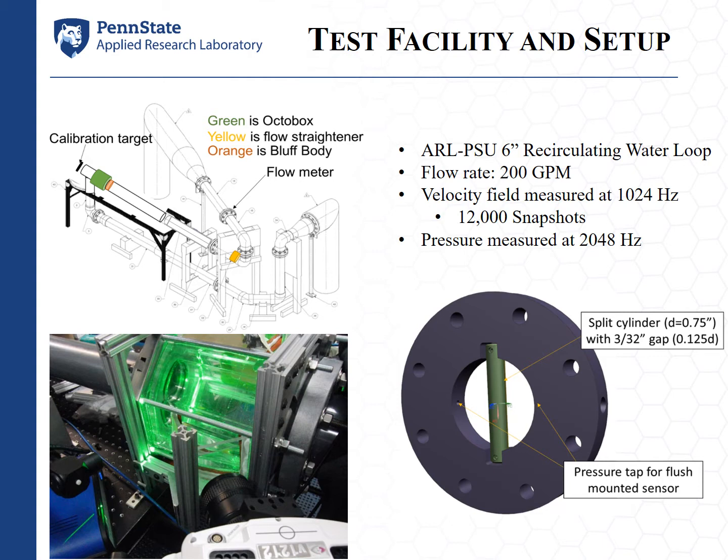So in this work, a split cylinder was mounted upstream of the optical test section. This optical test section is an acrylic pipe surrounded by a water-filled octagonal acrylic prism. This gives us flat surfaces with which we can observe the flow using 4 Photonics V1212 cameras mounted in a cross pattern around the test section.